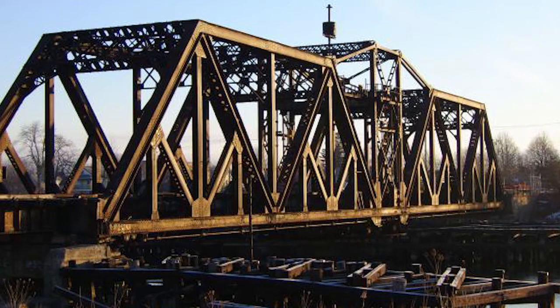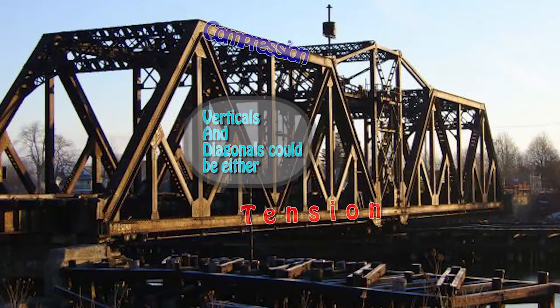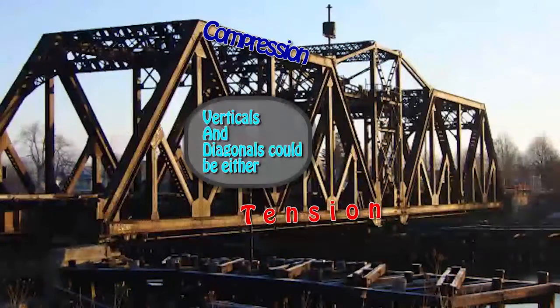During Phase 2, you can make use of some of the knowledge which you gained from Phase 1. For example, the top chord of your truss is going to be in compression. The bottom chords of your truss will be in tension. Depending on the orientation of your truss verticals and diagonals, these may be in tension or compression. Members in compression are subject to fail by buckling.